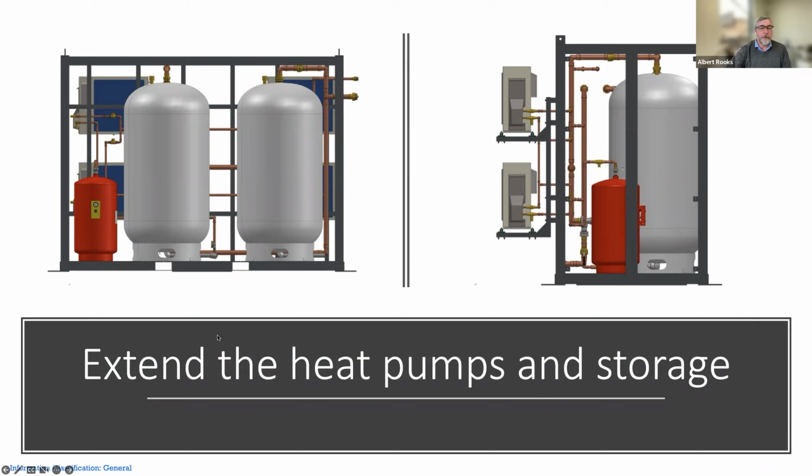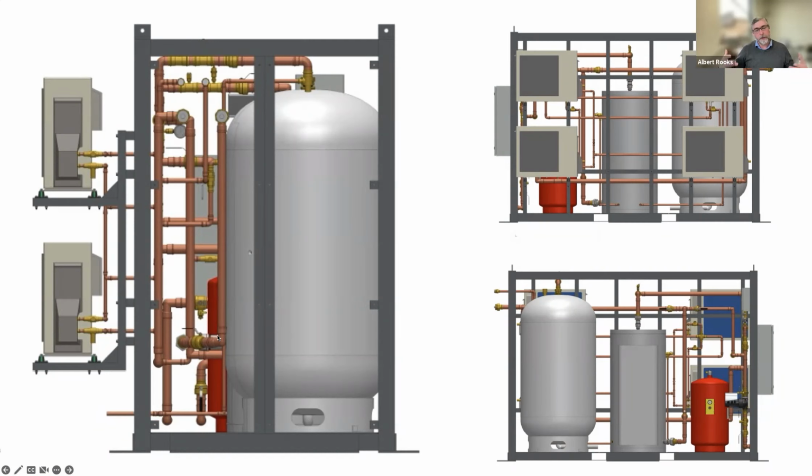So if I go back and look at the configurations that the industry can work with, there's another packager called Origin in North Dakota, and the two companies offer very, very similar solutions. This particular skid, in the lower right-hand corner, has all of the things that a plant needs, but it's only got so much storage capacity and so much heat pump capacity. But we've got the power landing, the recirc pump, the swing tank, the controller, the temperature maintenance valve, everything we need for a basic plant.